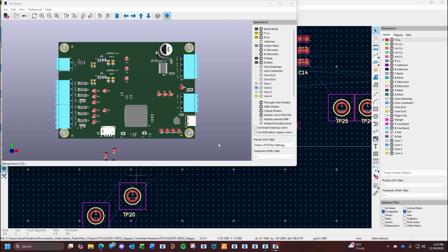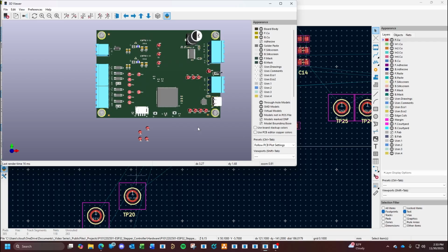So I actually created a library for the step files and went in and updated all the footprints to properly have the information, to have the proper step files. If you download the project from GitHub and change your directory structure for everything, you may have to readjust all of them, but they'll all be there. You just have to point them to the new directory and then just follow suit for future work. So now all the 3D step files will be present on the PCB.